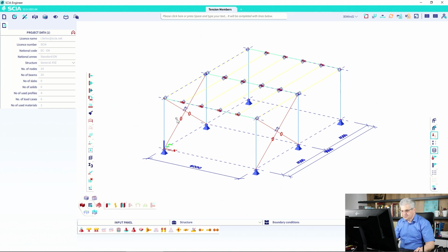So we have defined the structure, and we need to calculate nonlinear, that means we have to explode the standard Eurocode combinations to linear combinations and read them to the nonlinear combination. And then for each nonlinear combination, one structure will be calculated. Because in the nonlinear calculation, the principle of the superposition is not valid, so we have to create first the nonlinear combinations with all loads, with safety factors, and then perform iterative the analysis.